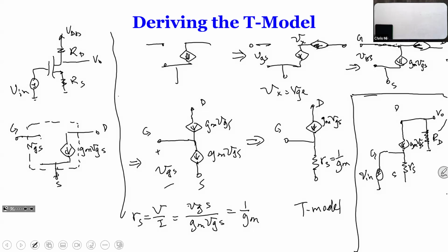Okay, last one, what is connected to the source? Through a resistor to ground, which is capital RS. So on this circuit, where do we mark our VGS? This is the voltage across RS. Oh, it doesn't go away. So your VGS is the voltage from gate to source. So this is your source, and this is your drain.